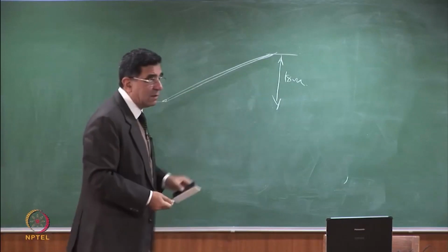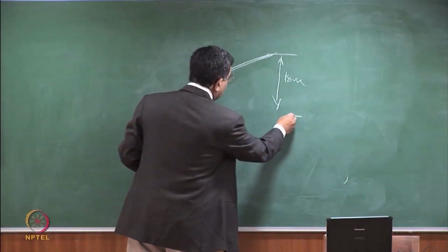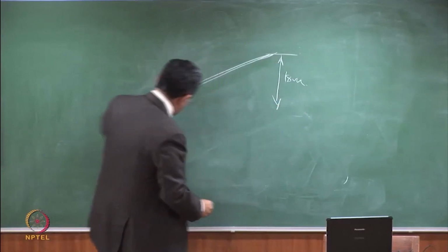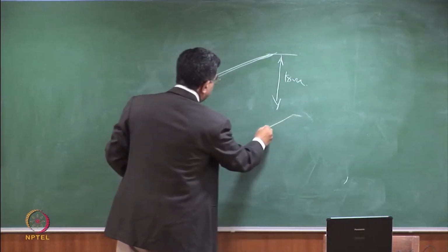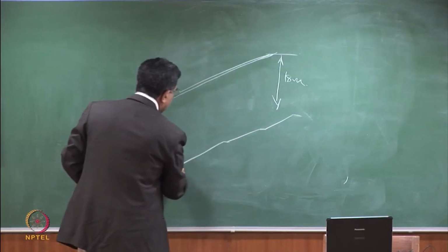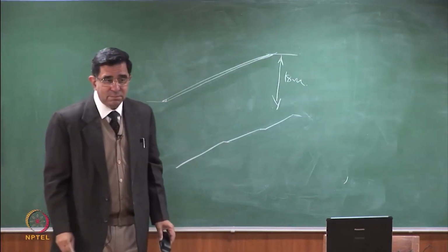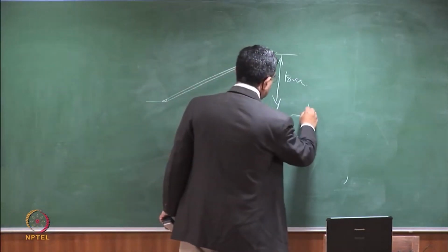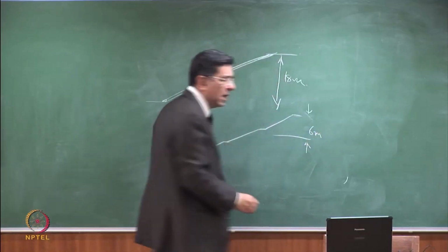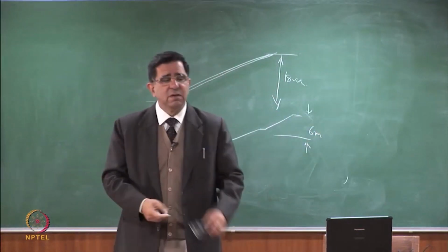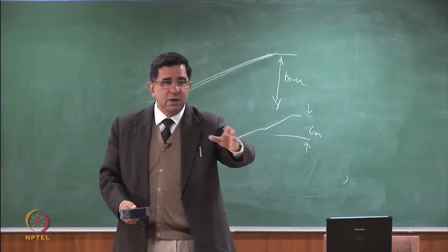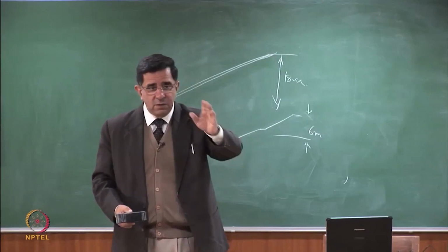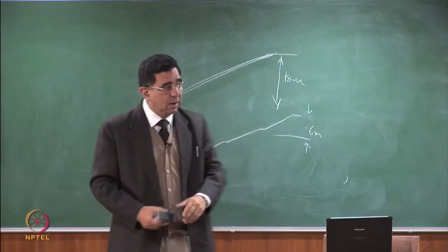So when you will have a landfill of this type, your natural thing will be, sorry, I'll redo this. At every 6 meters there should be one. So there will be 3 berms. Now this gets interesting. So this is 6 meters high now. Okay. Typically, if you go read the railway manual for railway embankments or any other manuals, they'll say, please put a berm every 6 meters. You don't need it from slope stability point of view. You need it from erosion control point of view, that when the water falls down, the gully formation doesn't take place and it breaks the speed of the water.